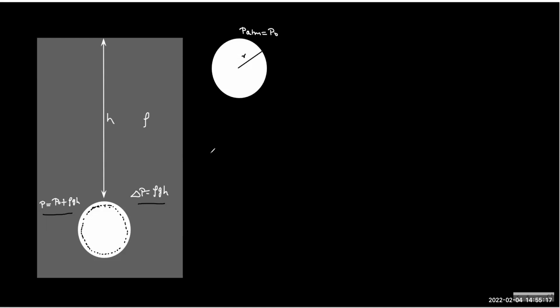So excess pressure is the issue of a blast. It is not the pressure. The pressure is already there. Everything is designed for a certain pressure, but if fire catches, then the entire 14 liters will try to expand at once, and expansion of gas is an adiabatic process, so it will create tremendous pressure which cannot be withstood by the iron shell. Okay. And if you want to prevent that, then you have to make the cylinder thickness maybe 10 times more. Now, that will be very costly, right? We also have to think of budget or economy.